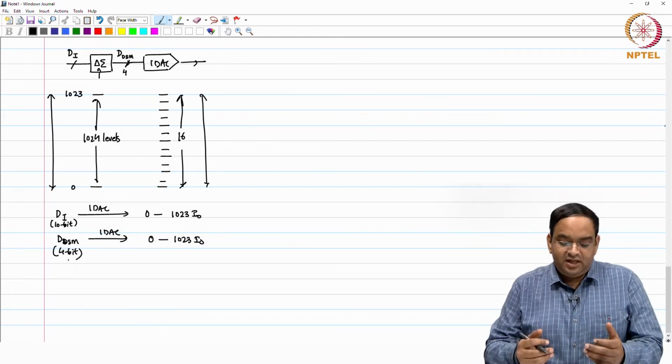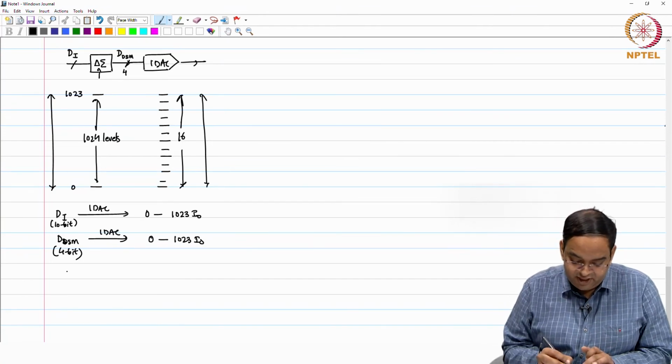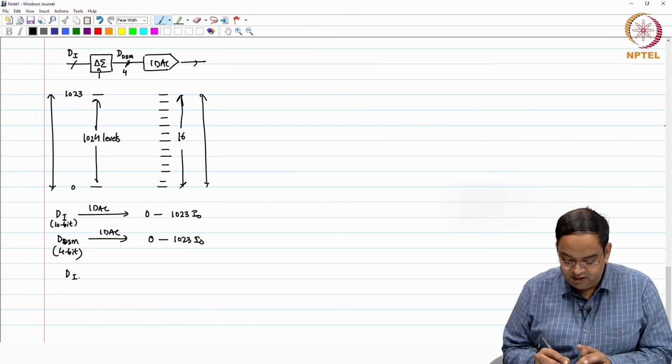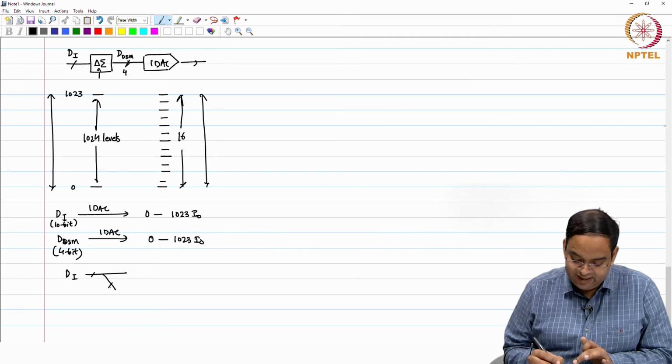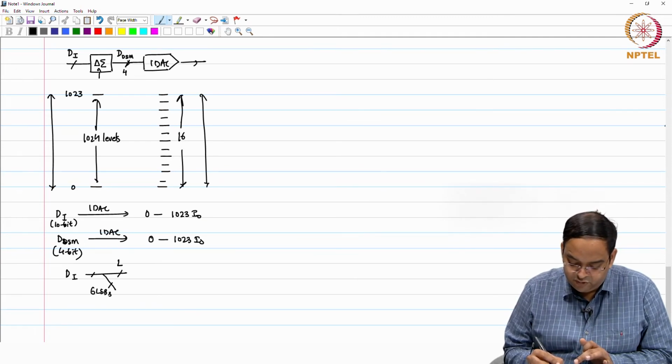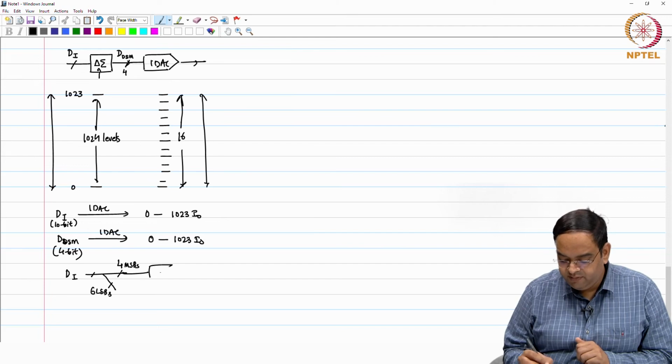You can think about it, the easiest way to do it is that I take this 10-bit number DI coming in, I drop 6 LSBs and I just take 4 MSBs, and I control the same IDAC.